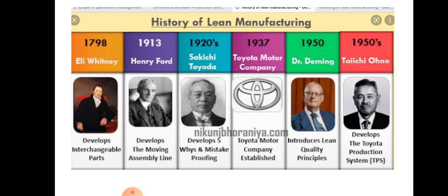And in the second section, the right process will produce the right result. So in this, the principle they followed is to create a continuous process flow to bring problems to the surface. And the third principle is use pull systems to avoid overproduction. That means when there is a demand, then only provide the downline customers in the production process with what they want, when they want, and in what amount they want, right? The material replenishment initiated by consumption is the basic principle of just in time. So that is called use pull systems to avoid overproduction.